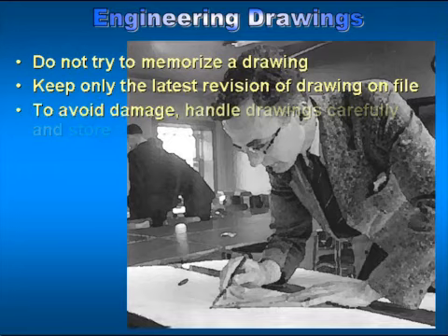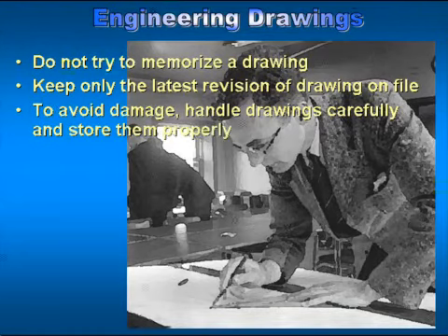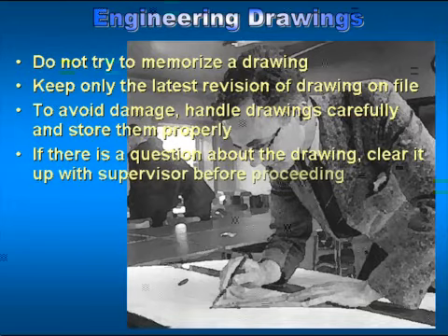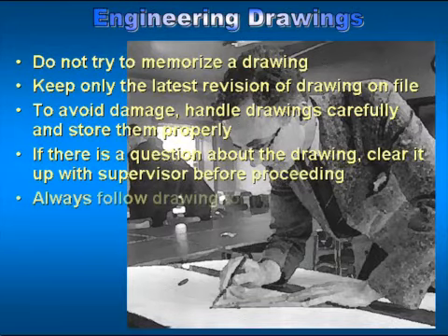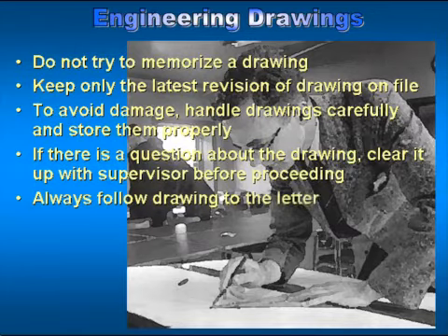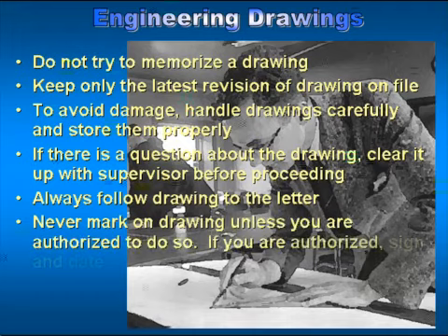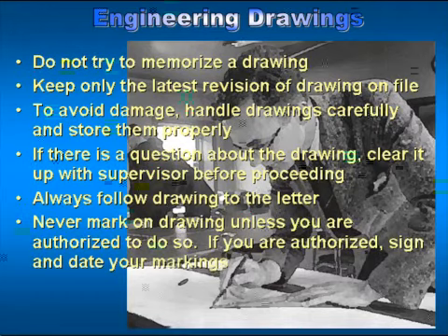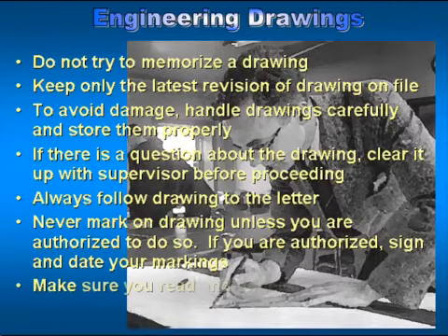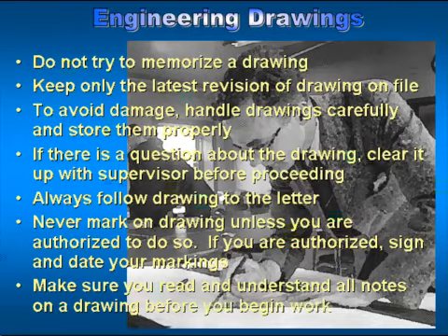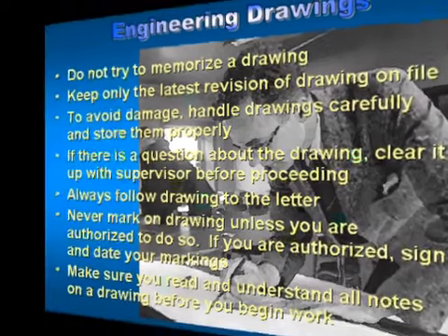To avoid damage, handle drawings carefully and store them properly. If there is a question about a drawing, clear it up with the supervisor before proceeding. Always follow the drawing to the letter. Never mark on a drawing unless you are authorized to do so. If you are authorized, sign and date your markings. And last, make sure you read and understand all notes on a drawing before you begin to work.